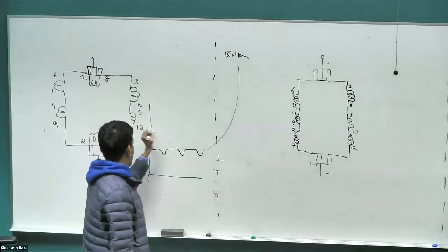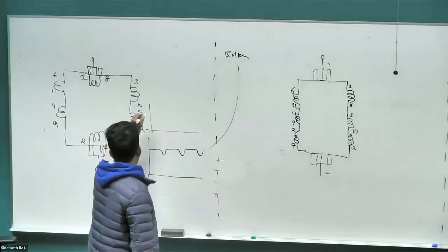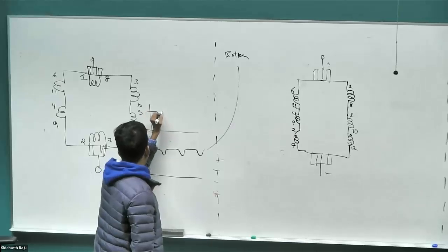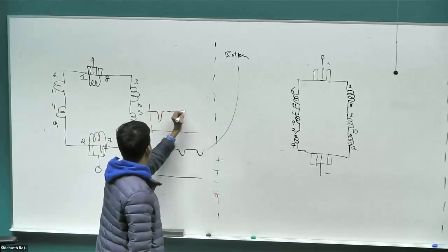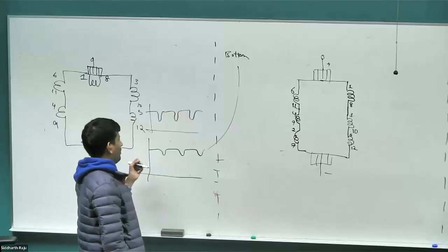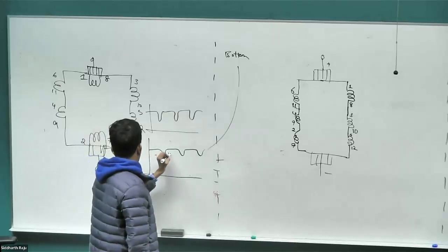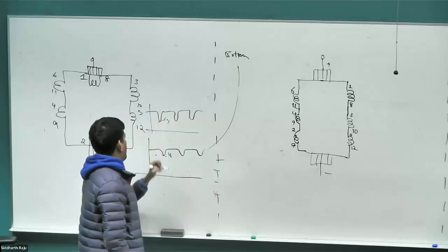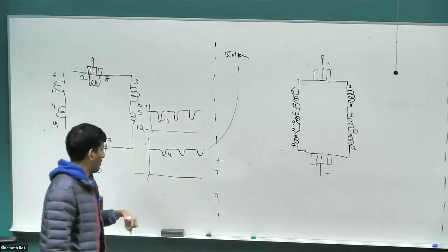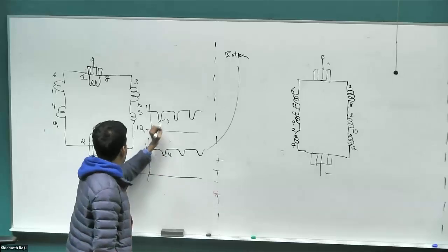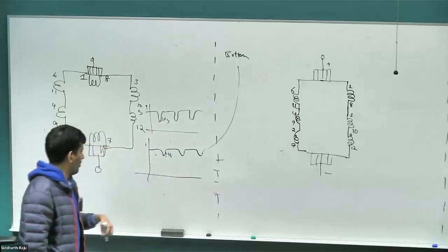In our case, the dip would be a little bit more prominent because 1/3 of the coil has gone out of the picture, so the voltage would drop by 1/3. But if you have 6 coils, then 1/6 of the coil would be dropped out, so the voltage you can expect drops by a factor of 1/6. Right? If this is 1, it is 1 minus 1/6, versus minus 1/3.